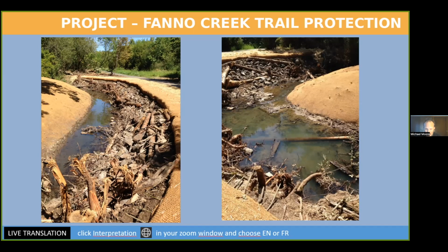Also, you can see just under the soil lift that's over the top of the structure, there are willow cuttings that have been laid in beneath. And there will be an entire planting campaign that goes in over this, as Bob mentioned, because it's critical to make sure that the vegetation that is planted takes hold before this really takes on a heavy flow.